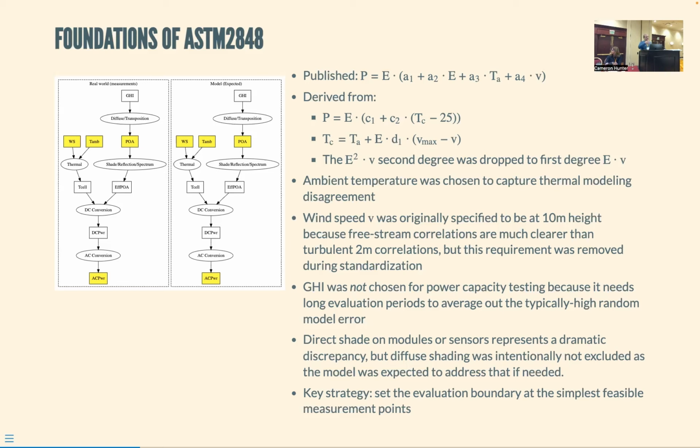And that's really where I come into saying, let's take an outboard measurement instead of sticking a pyranometer underneath the array amidst these complex shading situations. Put it outside the perimeter of your array where the irradiance is more stable, and you will end up with a bias, but you can account for that because this is a capacity test and it uses regression, so it can adapt to that bias.